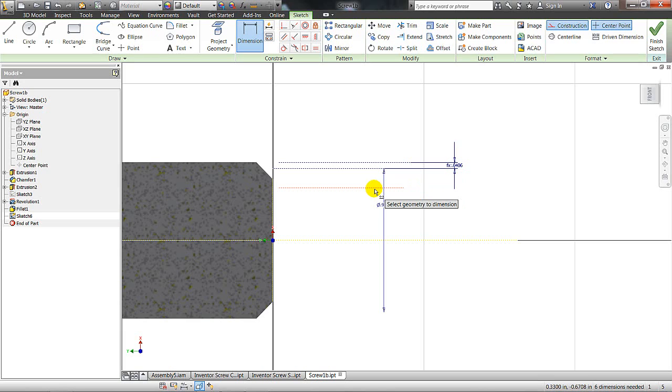And then the bottom of the thread, checking my chart here again. Okay. The bottom of the thread, from top of thread to bottom of thread, is 0.625 times H-depth. Okay, that sets the top and bottom of my thread for me.